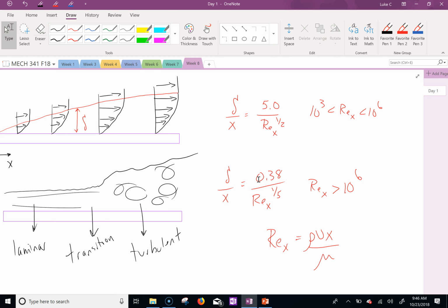Everything is going to have a boundary layer, no matter what. As I'm walking here, I have a boundary layer that sticks to my surface. But as I'm walking here, I have a lot of pressure drag, right? Because I have a lot of frontal area here. If I turn, I have less pressure drag and a little bit more surface drag. But as I'm walking, what's happening to the flow behind me?